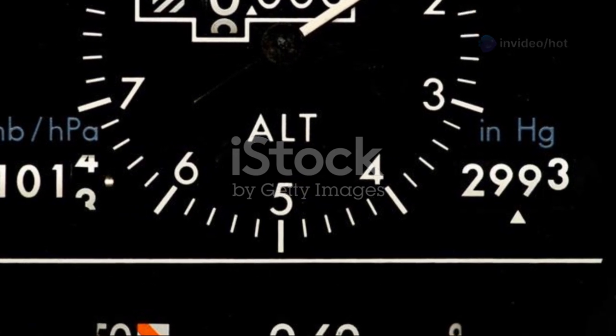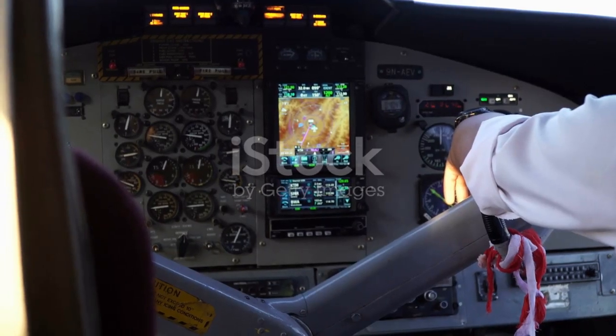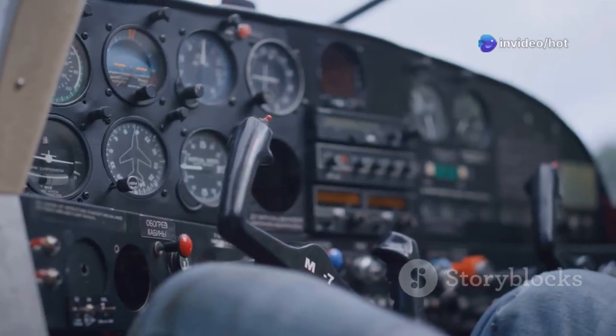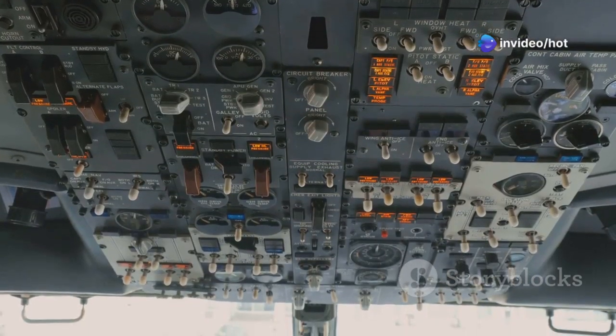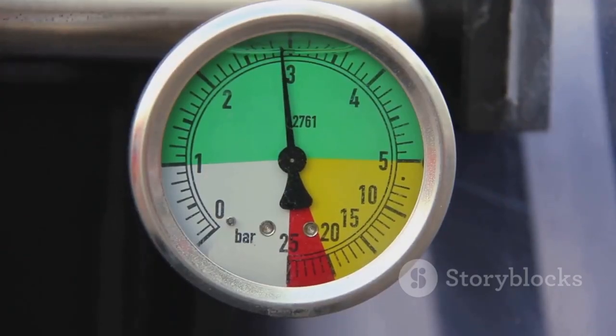Section 5, Transition, where altitude becomes flight level. Transition altitude is crucial. Below it, aircraft use local altimeter settings called QNH. QNH gives altitude above mean sea level. Above transition altitude, pilots switch to flight levels. They set altimeters to 1013.25 hPa.